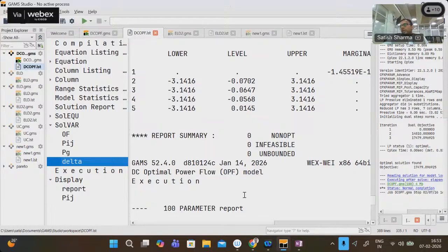I will share this code, and I recommend comparing it with what we have written in MATLAB for DCOPF and economic load dispatch. Compare the results and see how the variables are defined, whether they give the same results, what the values of the dual variables are, and what the generator outputs P1, P2, P3 are. If they are different, try to see why.